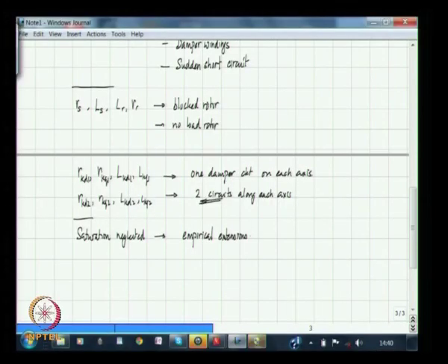Of course, once you incorporate this into the machine model, you can't do any analytical solution of the equations. One has to resort to numerical simulations in order to get at the behavior of the machine. Even without that, the equations are fairly involved, and analytical solutions, as we have seen in the case of synchronous machines, can become very involved. So one can look at what these extensions are in order to represent saturation in machines.